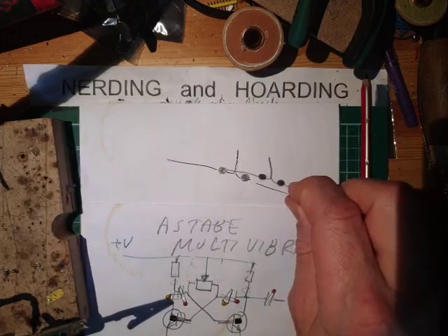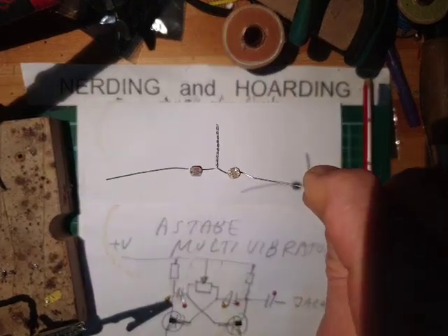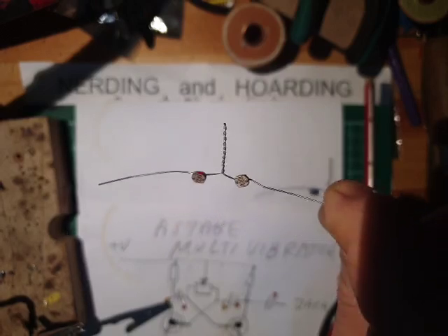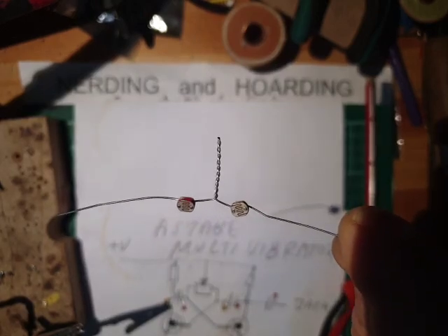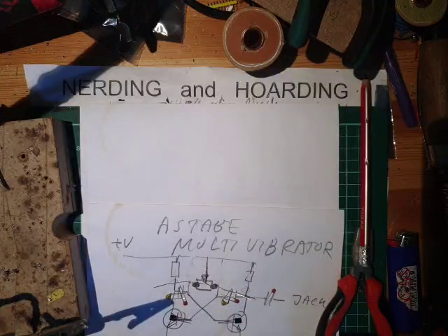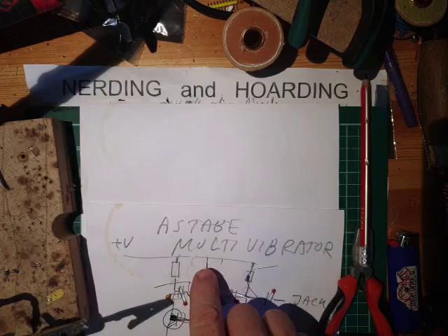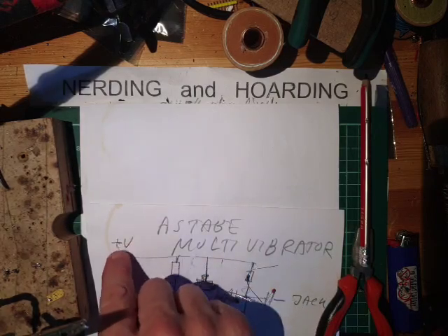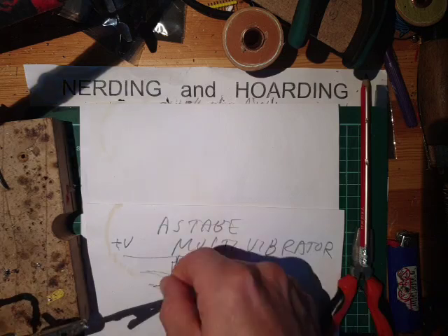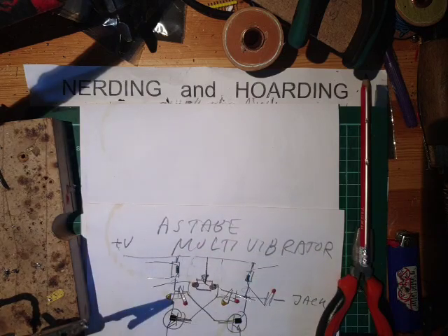So here I invented the potentiometer, the light dependent potentiometer. So this is one component, otherwise this project will fail due to too many parts counting. If you want to add voltage control to this, you can do it by removing this from the incoming voltage, the V plus, and put it to CV. But we're not doing that today.